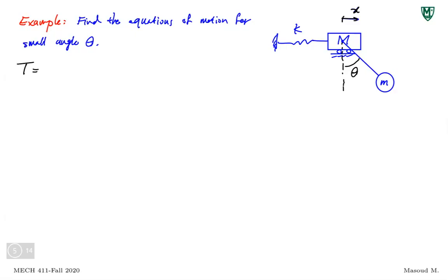I remember from dynamics, we had relative velocity and absolute velocity. Relative is with respect to some specific moving frame, maybe. Absolute is with respect to, let's say, the Earth reference frame, with respect to a fixed system on Earth. Well, Earth is moving itself, but we're finding the velocity with respect to a reference frame on Earth, and that we call the absolute velocity. Relative would be if I find the velocity of an object with respect to another object that is moving. So the v in that equation is absolute velocity.